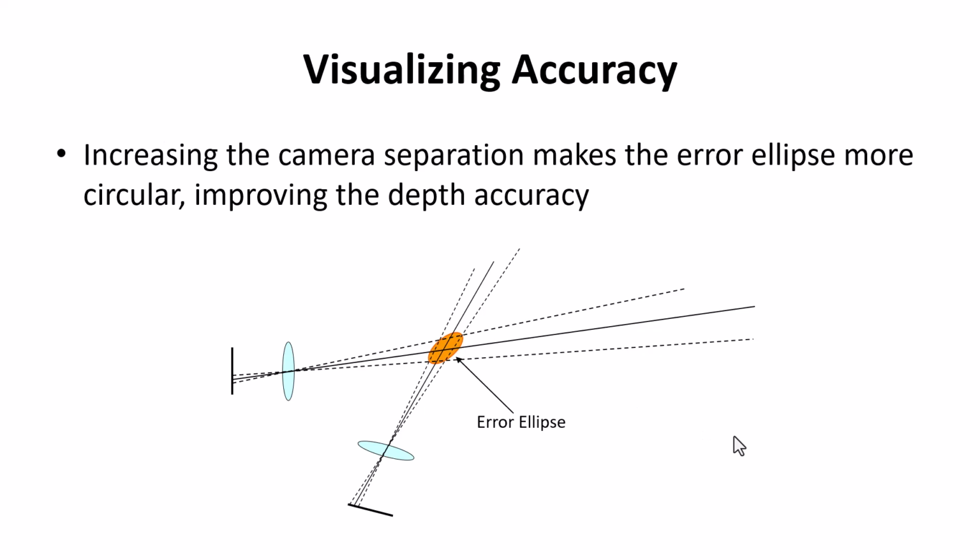So we often need to give some thought to how far apart the cameras should be to get optimal accuracy out of the 3D points. And as it turns out, if you move these cameras too far apart, the whole process starts to not work well, because the image seen from one camera looks vastly different from the image seen by the other camera of the same object. So they look quite different, and the image matching process within photogrammetry starts to break down. So there's a sweet spot: far enough apart, but not too far apart, to get the optimal performance out of your software.